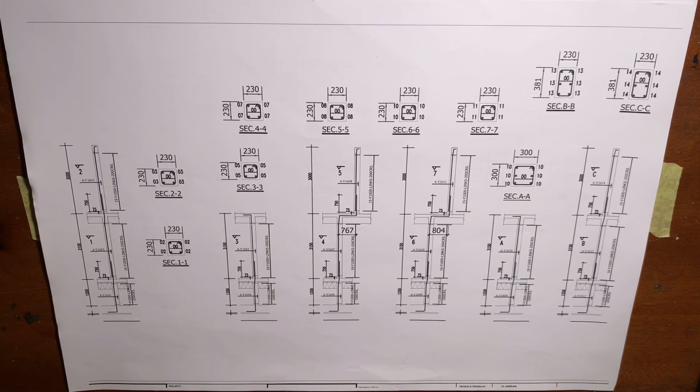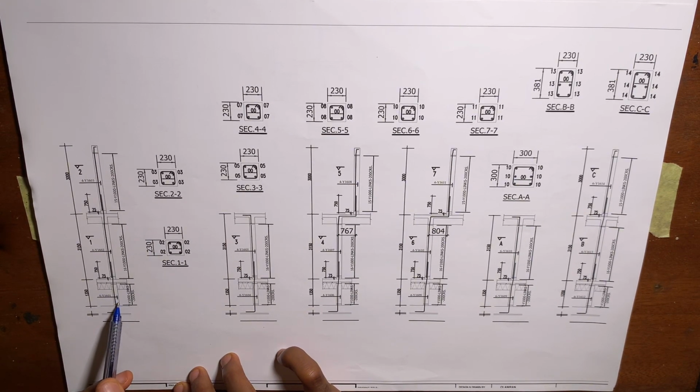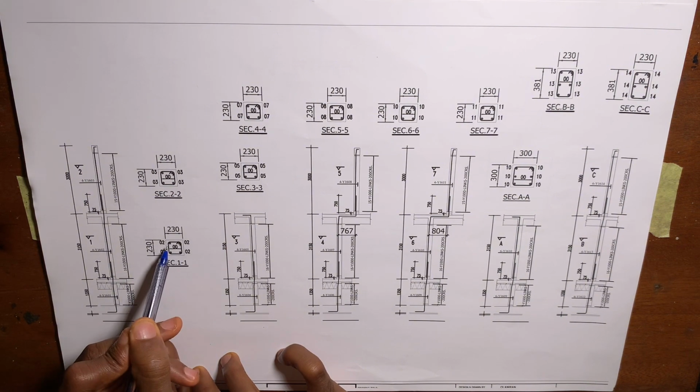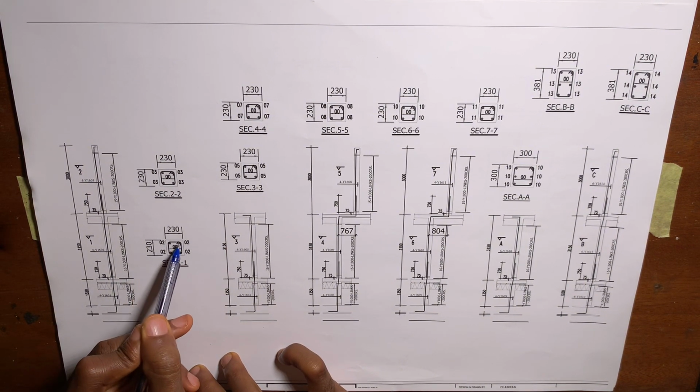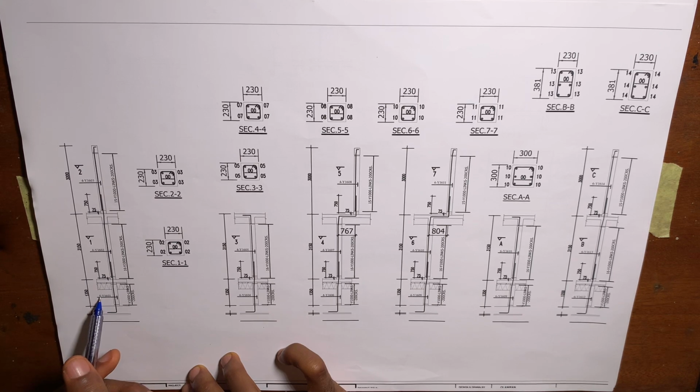Now if you look at this drawing, starting from the substructure, you can see there's a horizontal line, and on top of this horizontal line they say 4y16-01. What this simply means is that the type of reinforcement we're going to have for this starter column is y16, and there will be 4 in number, just as you can see these dots from this section, right? You can see there are 4 in number, 1 2 3 4. That is what it's simply telling you, 4y16. So the type of reinforcement used to make this starter column is y16, and there will be 4 in number.